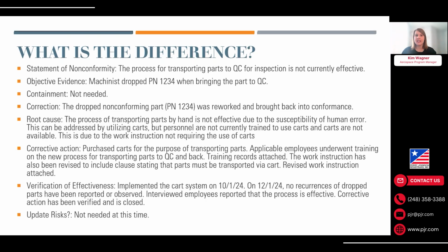In this situation, containment wasn't needed. The correction says the dropped nonconforming part number 1, 2, 3, 4 was reworked and brought back into conformance. As you can see here, the correction is written in past tense, and it does also reference the specific part number that we're talking about from the objective evidence. So in terms of when we review third-party corrective action responses, correction responses, if the correction said the dropped part will be reworked, that wouldn't be acceptable. It needs to be written in past tense.